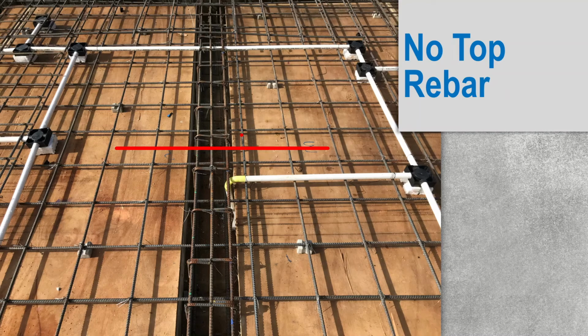You can't avoid that. There will be a failure in the slab because there is no reinforcement to carry the hogging moment due to fixity. This could lead to a structural failure. Therefore, we have to keep in mind to place top reinforcement at every support of a slab. Wherever you support the slab, there should be top reinforcement, except where it is a simply supported slab.